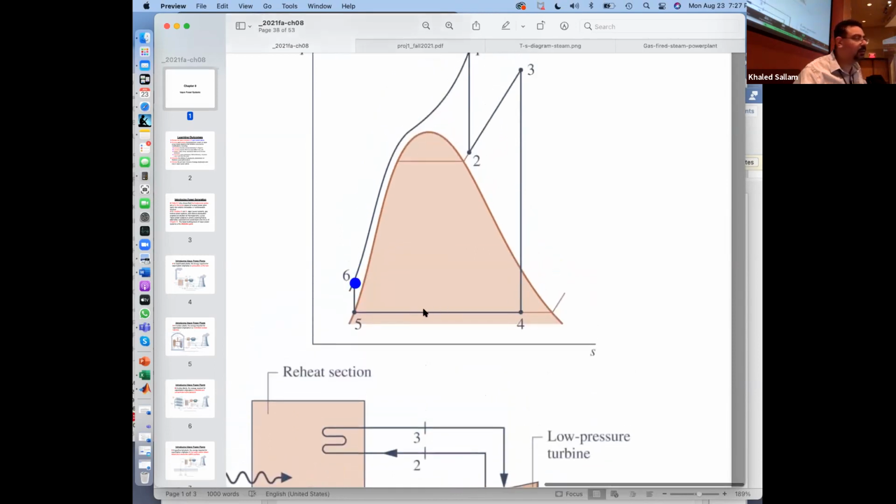But if you go here rather than here, the last rows of the turbine, the part that experiences this, are being shot at with droplets. A turbine that's here will live 1 year, and you have to scrap that turbine and get another one. This turbine will live 5 years. This turbine will live forever, right? But it has low efficiency. So yes, from the thermal side you want a smaller Q rejection, but from fluid mechanics, droplets hitting a plate that's moving very fast is horrible.